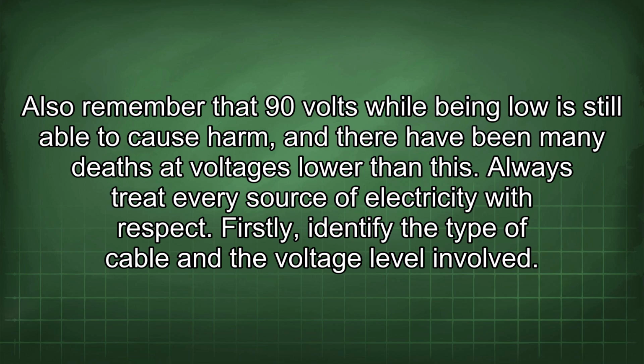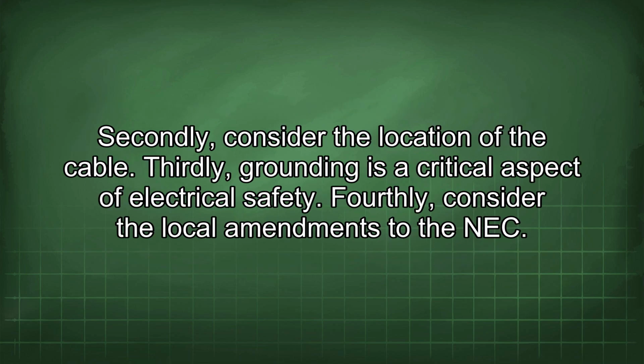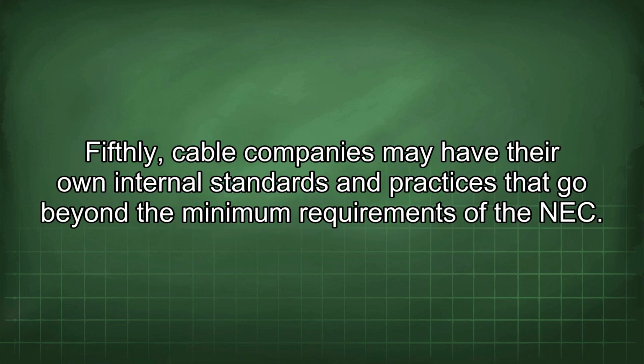Firstly, identify the type of cable and the voltage level involved. Secondly, consider the location of the cable. Thirdly, grounding is a critical aspect of electrical safety. Fourthly, consider the local amendments to the NEC. Fifthly, cable companies may have their own internal standards and practices that go beyond the minimum requirements of the NEC.